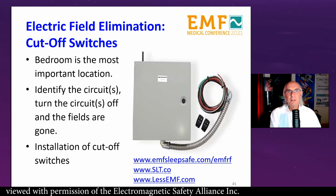What we do is we identify the circuits by actually flipping off the circuit breakers to find out until the field is collapsed, and then we know which circuits are involved in creating this field in this bedroom. And then we have an electrician install a box similar to this, and we have a little remote control. When we go to bed, we can flip the switch and the circuits are turned off,